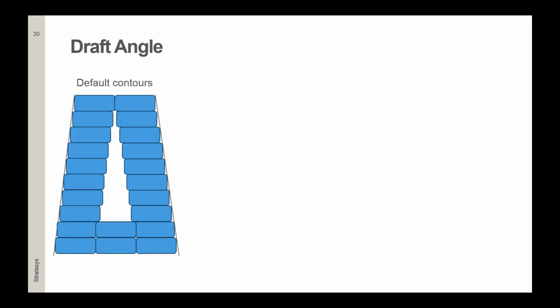Looking a little bit closer, when having 2 default contours, software will try to close the gaps by adding additional toolpath in between. And if the gap is thinner than the default toolpath, it will leave the gap inside empty, giving you less strength for the part. If it does not fill by the width, it will leave empty gaps, as I mentioned.